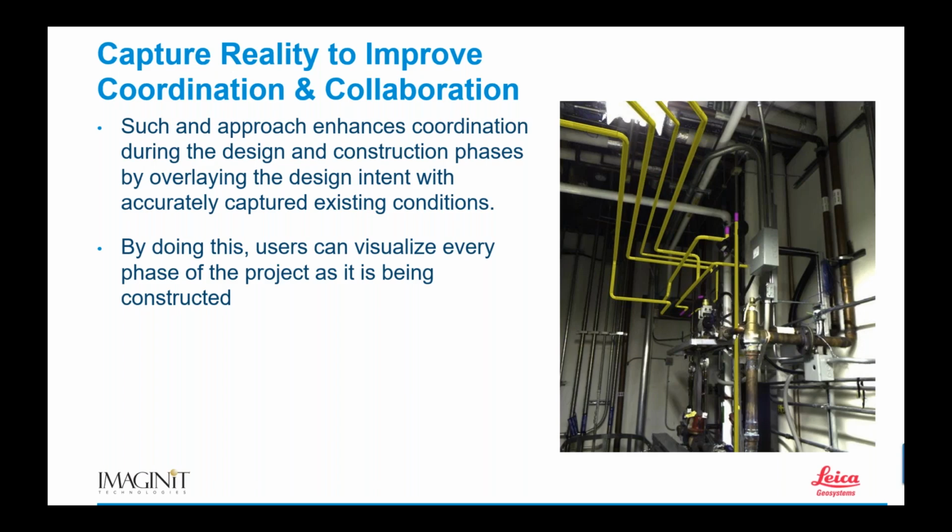Now, with what we are able to do with laser scanning, we bring that into AutoCAD Architecture, Revit Architecture, Revit MEP, SolidWorks, Inventor, MicroStation, Plant 3D. Try to cover all the bases there. Pretty much any piece of software I can get a point cloud into. Now I utilize that point cloud to route my new work. What am I doing? Why am I doing that? Coordination, collaboration. I'm now routing my new work piping based off the existing conditions.